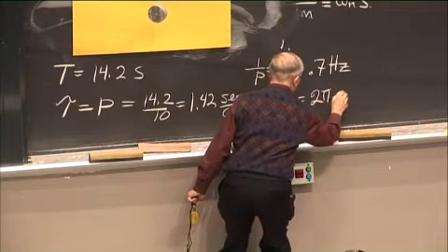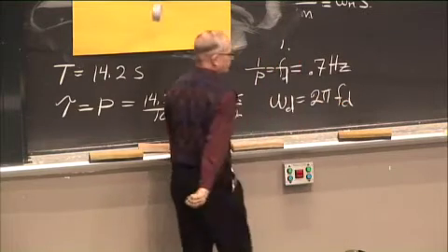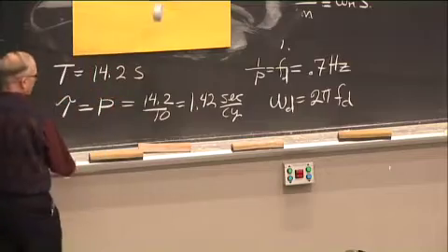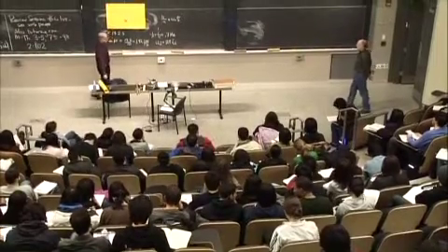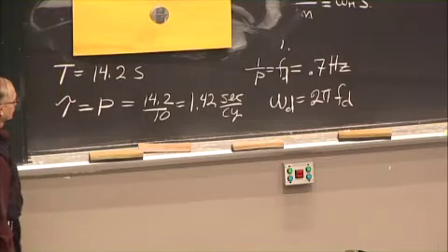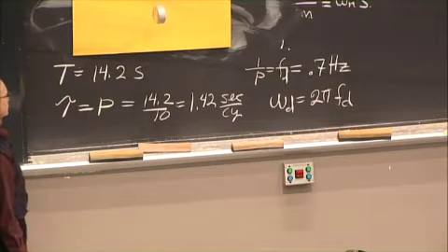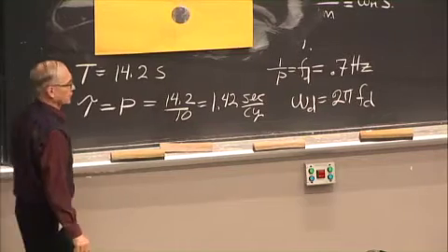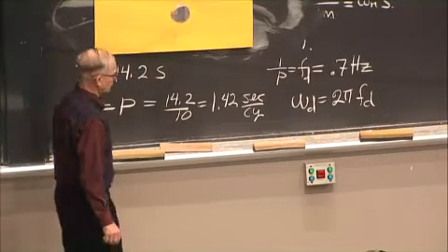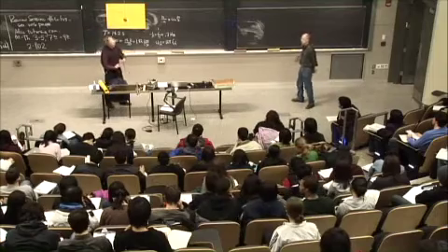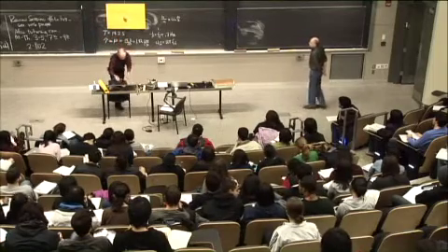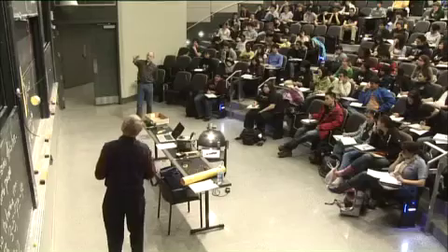We've always been talking about circular frequency, which is radians per second. Here's the relationship: 2 pi radians in a circle. So we multiply this by 6 point something, and you get about 4.3 radians per second. So we figured out omega d by observation, and omega d is pretty close to omega n, which appears in the equation.